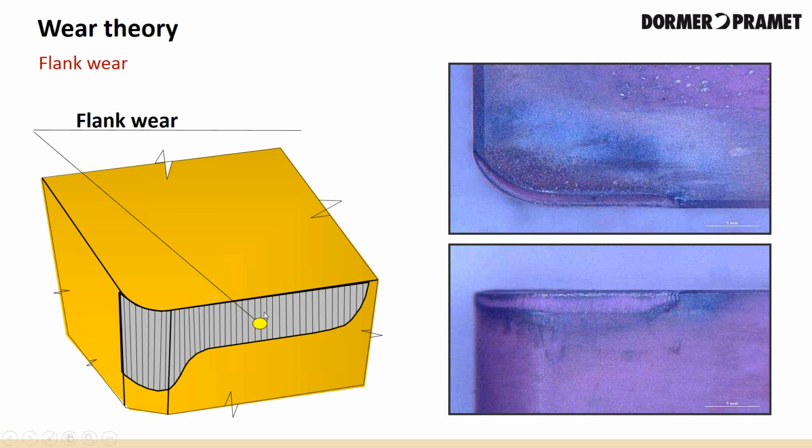When this wear gets to be 20 thousandths or 0.020 inches in length, it is time to index or change the insert. This wear normally would appear after 15 minutes of actual cut time, and universally, 15 minutes is what we expect to see on any cutting edge, and that is accepted throughout the industry. And that is cut time, not movement to or from, it's actual cut time.